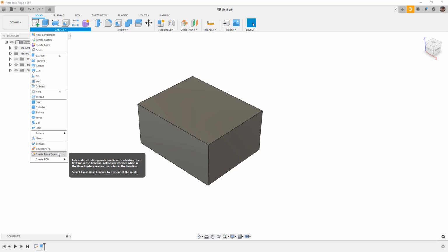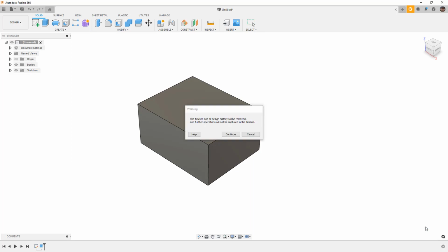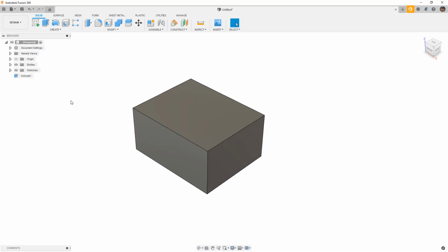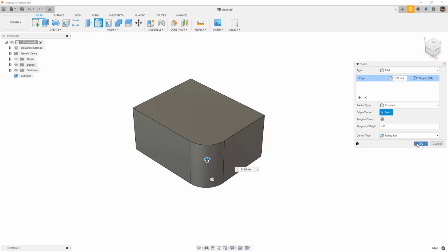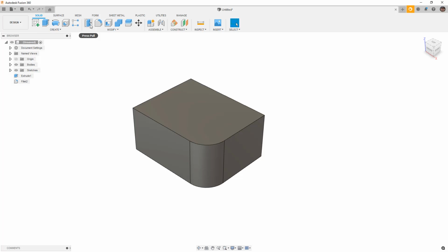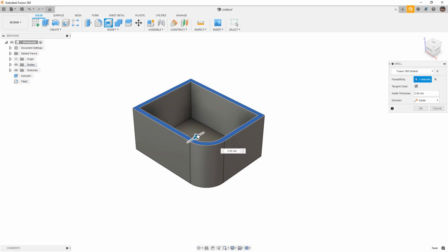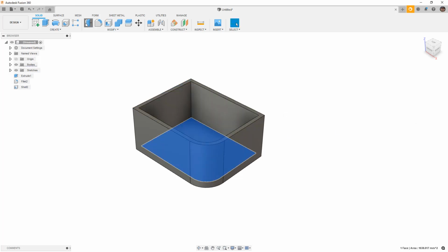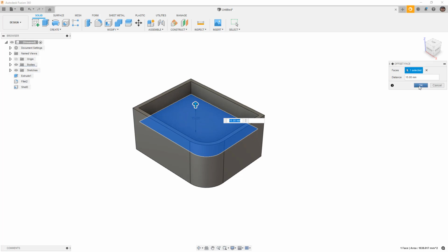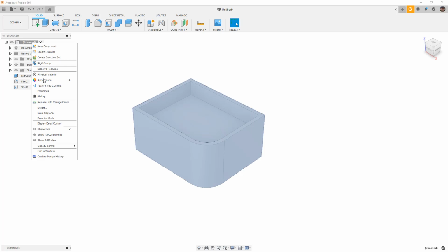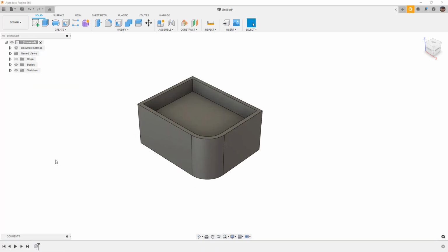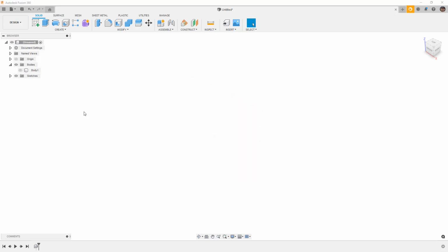When we're talking about modeling in Blender, this is typically done in a history-free nature, just like when we're working in forms. In Fusion 360, we can go down and turn off Capture Design History, and then we're working directly on the body. We can still do things like apply fillets to corners, we can make changes or adjust the shape. For example, if we want to shell this design, we can create a thin wall body. We can decide to move the bottom face by using direct tools like press pull, and we can adjust all sorts of details. At some point, we might decide that we're ready or we're done with the conceptual phase, and we can begin to capture design history again. So that workflow can be very helpful depending on what you're doing.